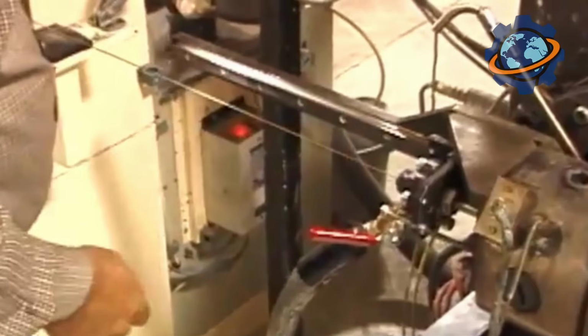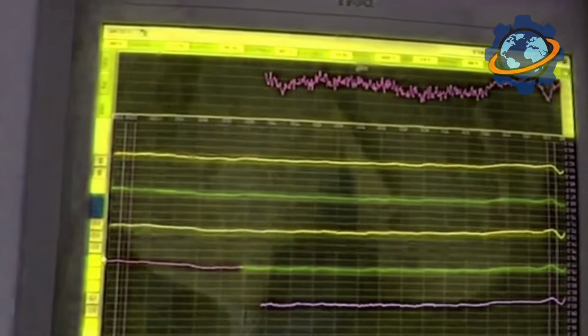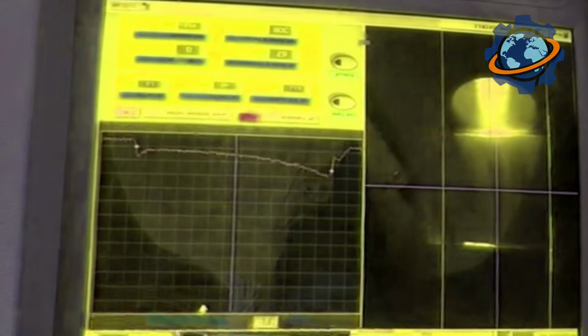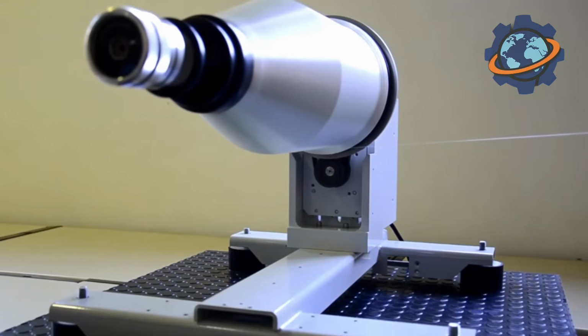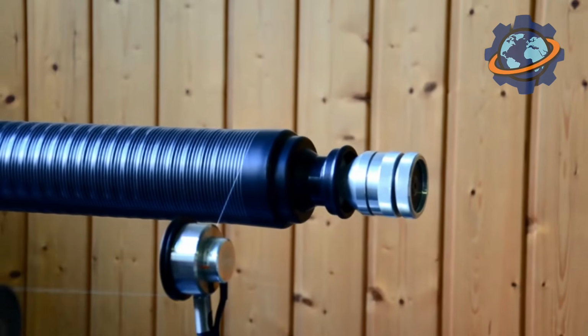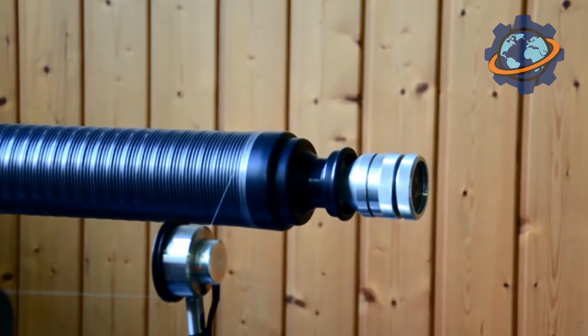The entire machine is equipped with sensors and control systems. They constantly measure the coating thickness, fiber feed speed, and uniformity of application. If the coating layer is too thin, or there are defects, the system either stops the process or adjusts the parameters to avoid defects.